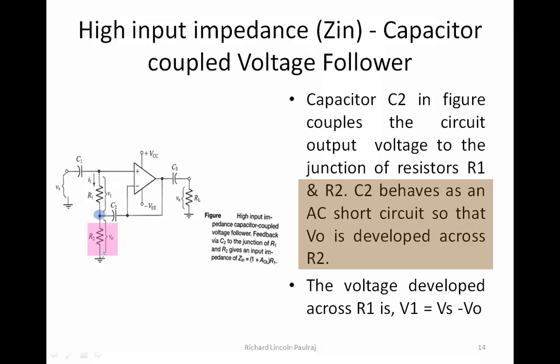Now, why is this so important? Because this line is actually the feedback line. Very important line, because this tries to stabilize your op-amp. As we have seen previously, positive feedback will bring in more oscillations, and then the op-amp doesn't remain stable. It becomes more unstable. So in order to have more stabilized outputs, we have negative feedback. Now adding to that, it's just like a cherry on the cake.